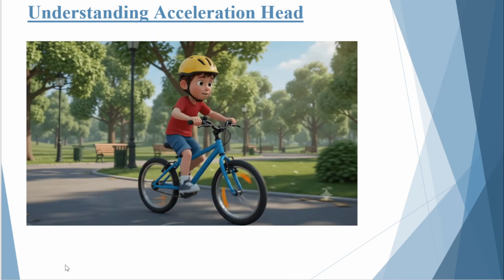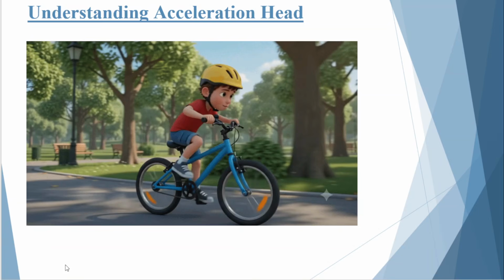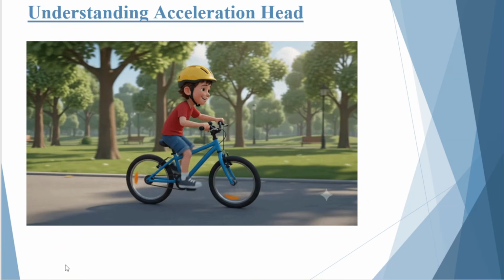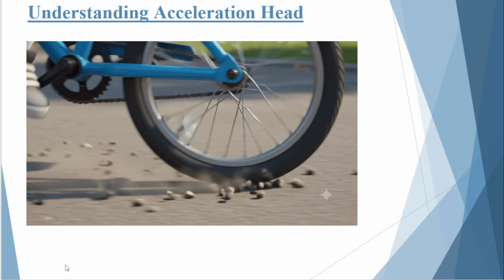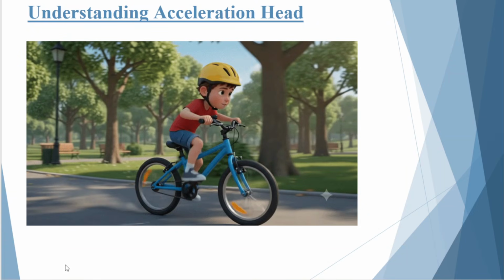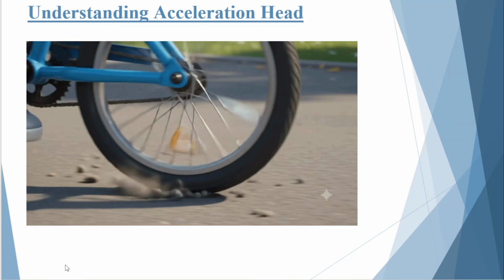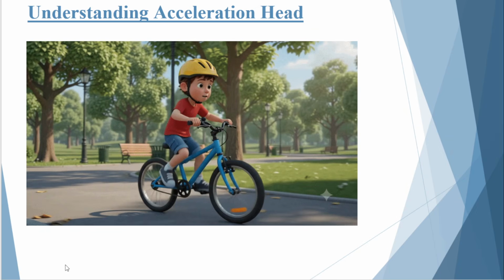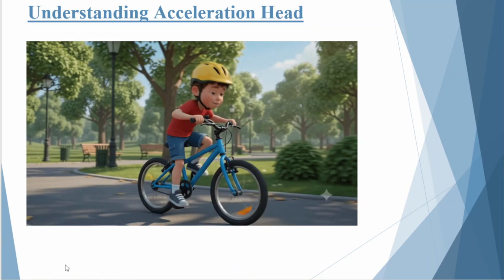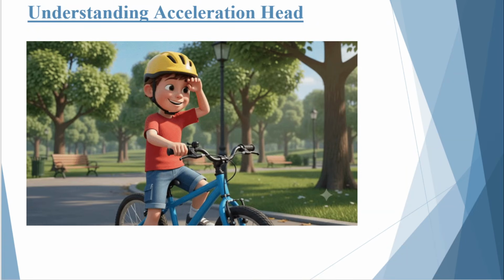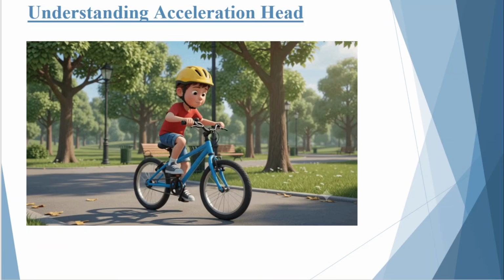Since the liquid inside the suction or discharge pipe is directly connected to the piston, the liquid column must follow exactly the same motion. When the piston accelerates, the liquid must also accelerate. Just like the bicycle, additional energy is required to accelerate the liquid because it has mass and inertia. In a pumping system, this additional energy appears as an increase in pressure head, known as the acceleration head.